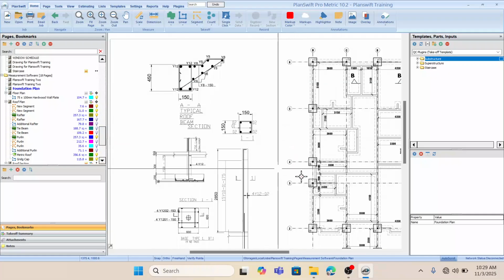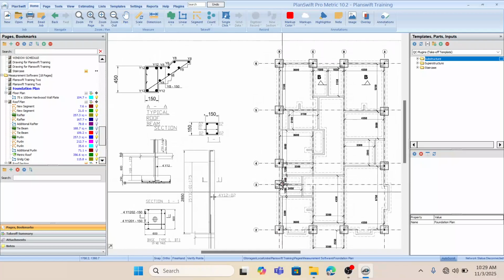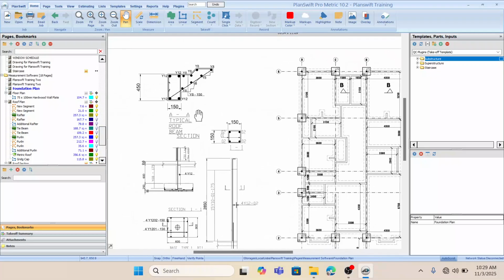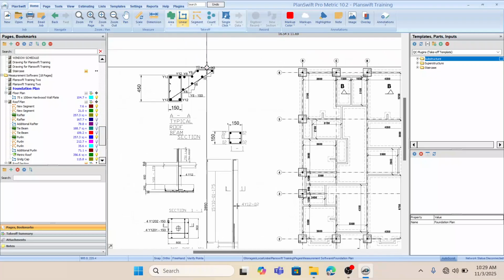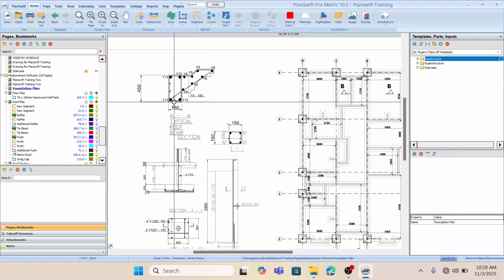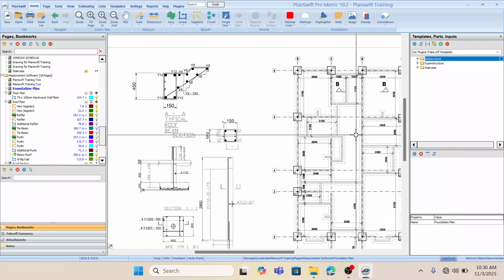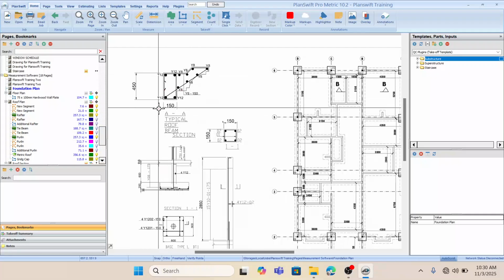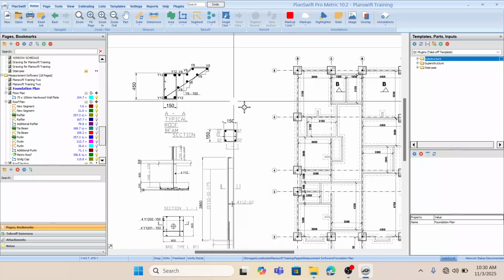Because I need this building perimeter, what I actually want to do now is make use of our area tool to trace the concrete area here. I'll keep that aside. Then I'll multiply that area by the perimeter. That will give me the value in meter cube, which is the value of concrete required for constructing this particular concrete work called the concrete fascia.